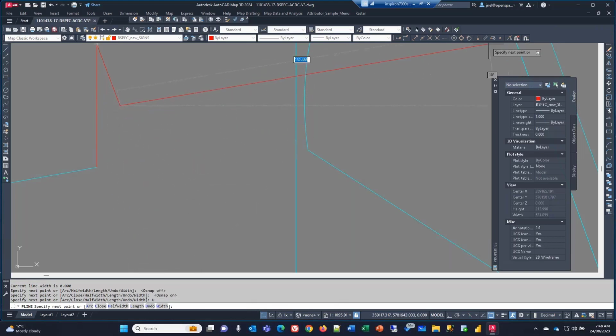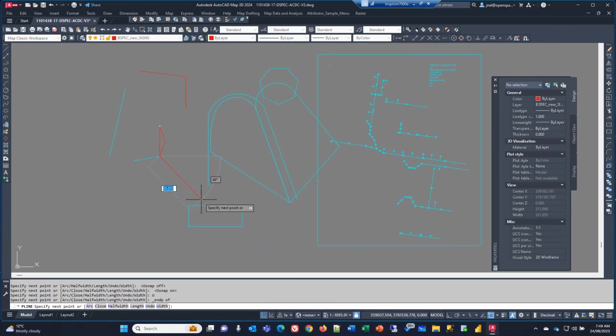The other one is then these snaps. So you can actually go and say, there I want to snap to endpoint. So go and pick that snap mode, and I want to snap to that endpoint. Or go and snap to an intersection or to an apparent intersection. So apparent intersection would be of this and that. So now you can see there, if those two lines were to intersect, that's where it would be.